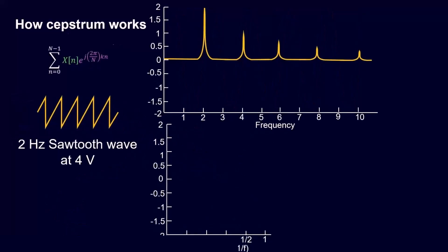This is how the Cepstrum works. We are applying the exact same principles, but now we're doing it, instead of in the time domain, in the frequency domain. And we're doing it to keep track of where the periodic components are. Sine waves and cosine waves are naturally periodic functions. So if you're looking for periodic components in a signal, a sine wave and a cosine wave is a good way to look for that. Really what we're doing is we're exploiting the FFT in a way that isn't normally used.